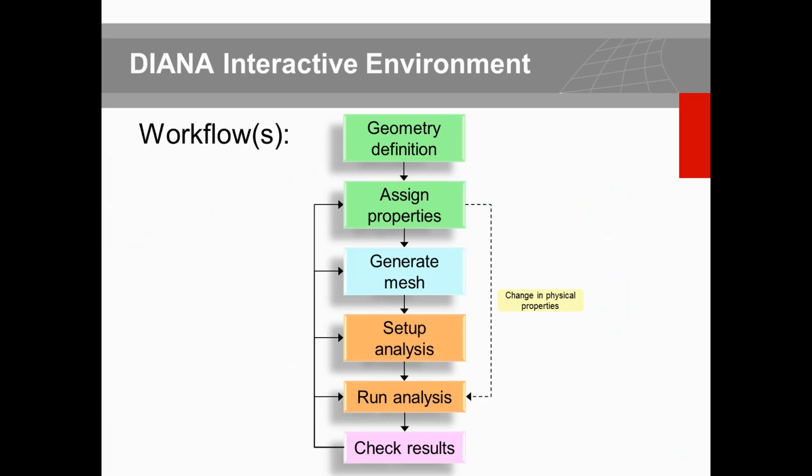After defining your geometry, you go for assigning properties. This could be in terms of the element type, in terms of interface, in terms of reinforcement, and so on and so forth. After having these assignments done, we proceed to the next level, which is generating the mesh and then setting up the analysis, performing the analysis, and getting and checking the results.